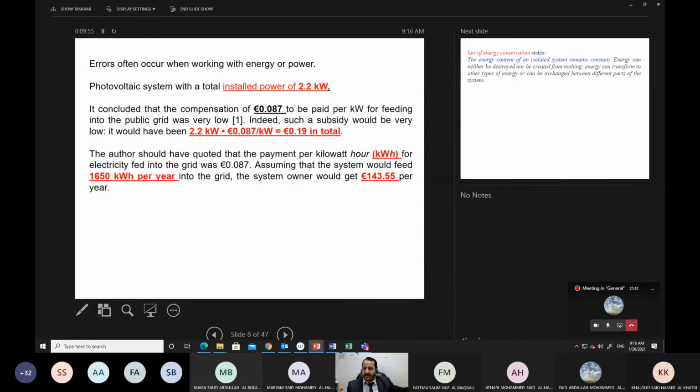When efficiency is low, the system is not good. 90% efficiency is a good system because the output over input is high. And when it is low, as an example 20 or 25, this is not a good system because the output over input is low. And this happens because the output is input minus losses. So when the losses increase, the efficiency reduces because the output reduces.